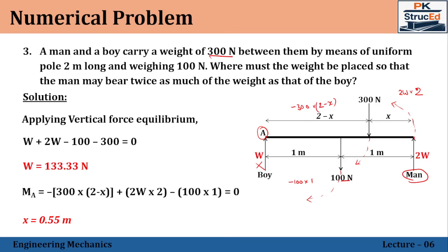To summarize today's lecture, Varignon's theorem will simplify the moment calculations. The resultant moment will be equated to the sum of the individual moments, and the theorem is extremely useful in non-concurrent force systems. In the next lecture, we'll continue with the applications of non-concurrent forces and couples.